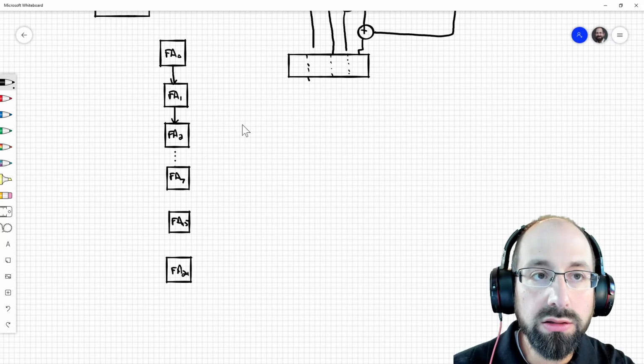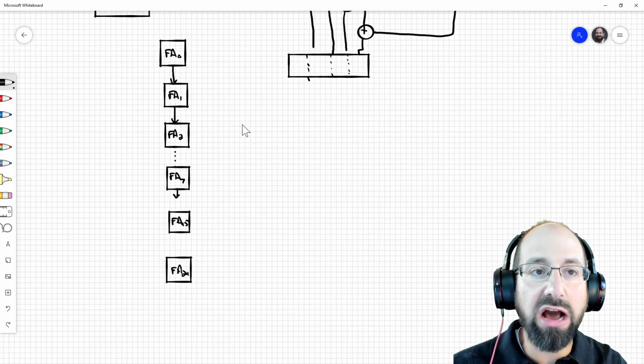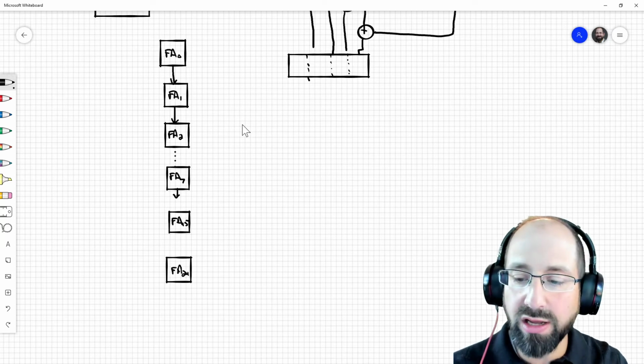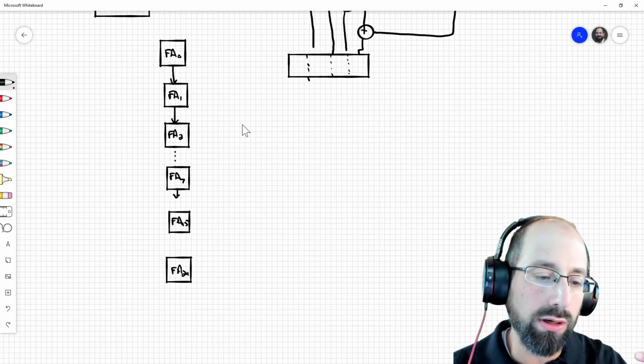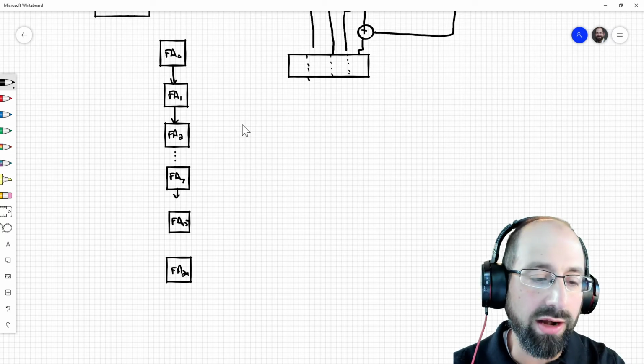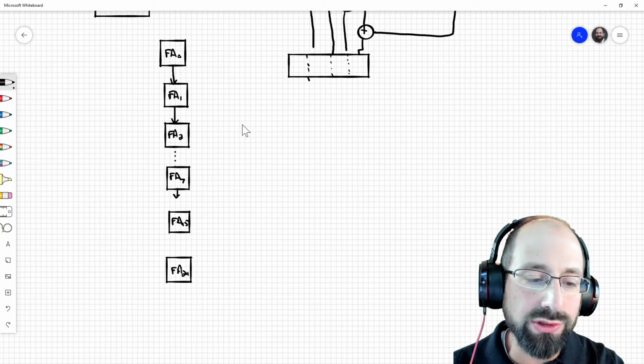In general, we have this carry chain in our design, where at the output of bit 7, that carry out should become the input to bit 8 of our full adder. That's for the conventional addu instruction.